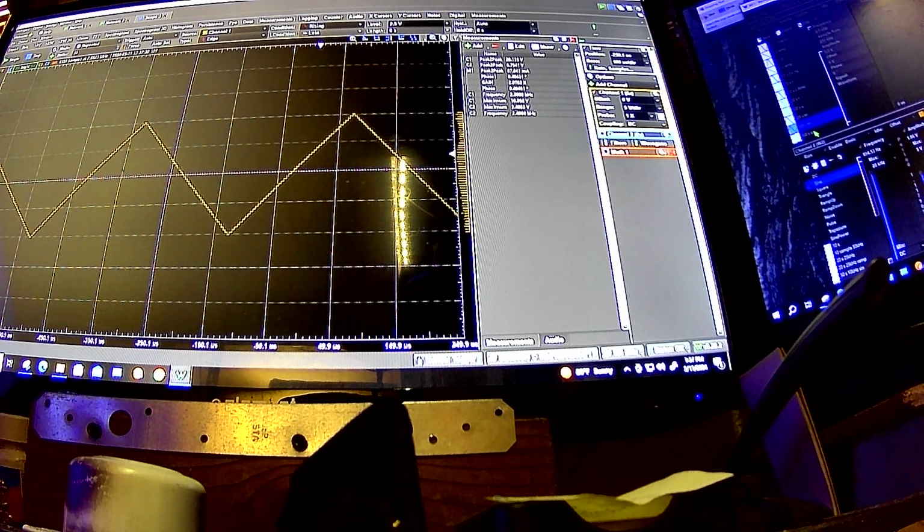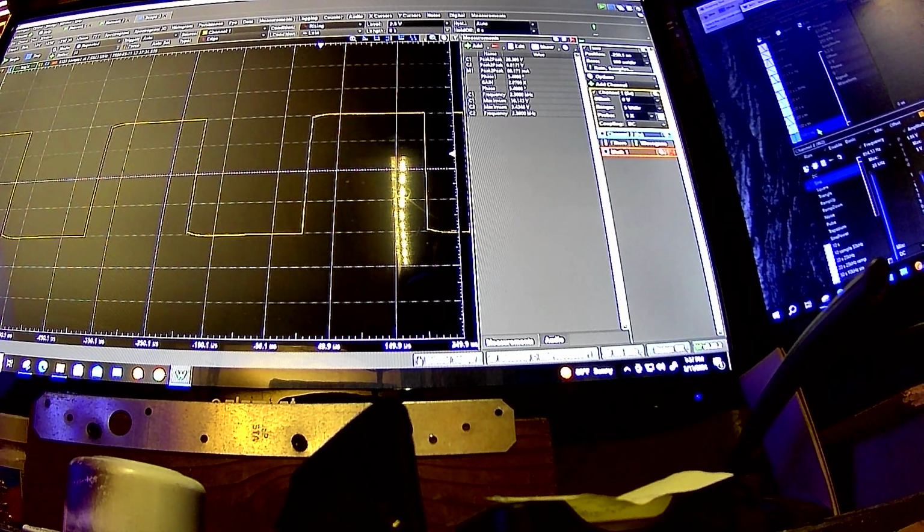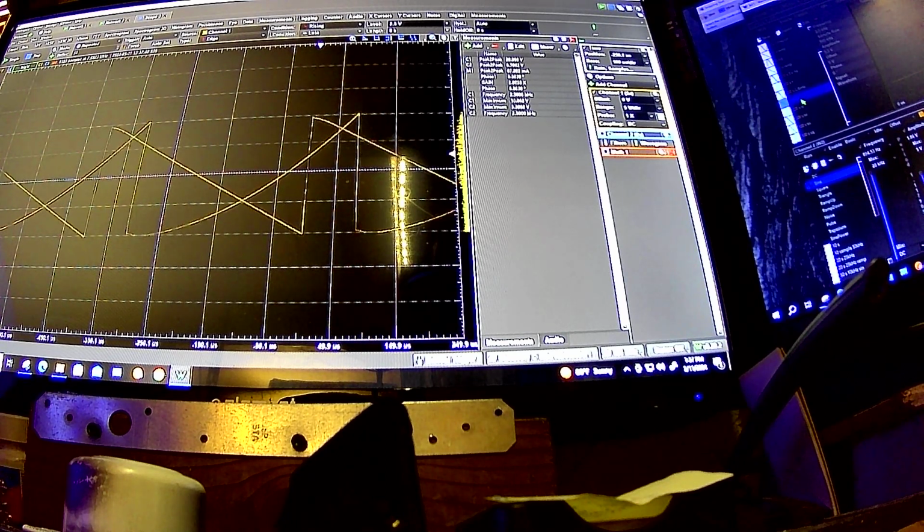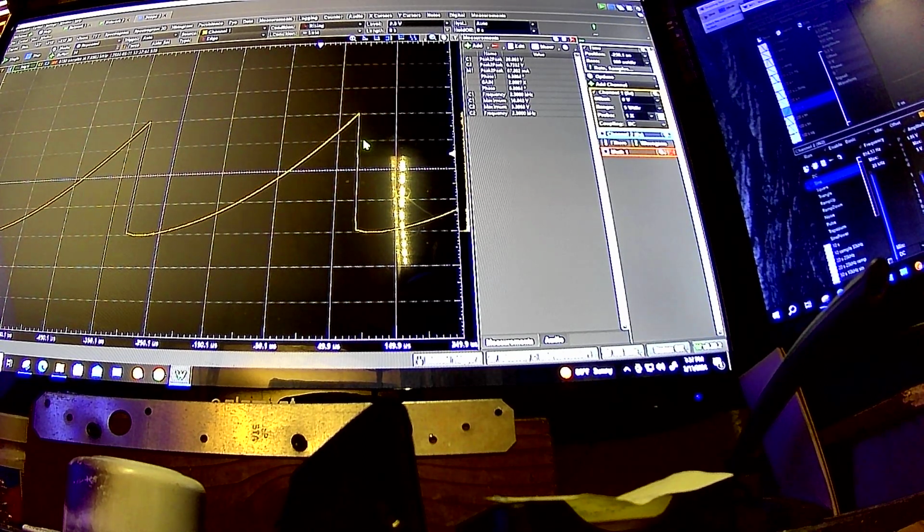That's 100 samples right there, and that's our other 100 samples. But they're looking smooth enough that you almost don't need filtering. Even though there are definitely some high frequency harmonics, they're going to be really tiny, and a simple filter would definitely correct that. It goes to show you the limitations of DACs, and why you really need pretty high frequency DACs, even if you want to generate audio signals directly, with no filtering.